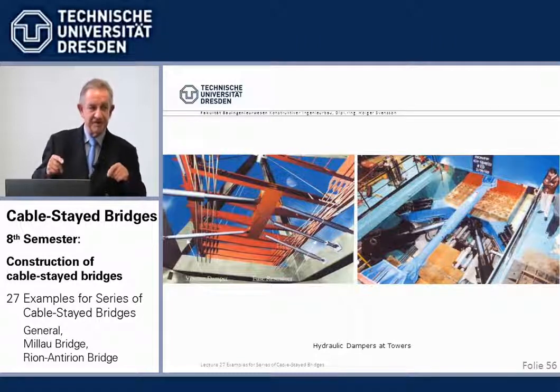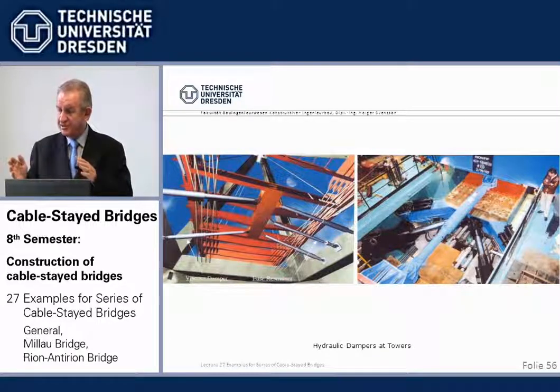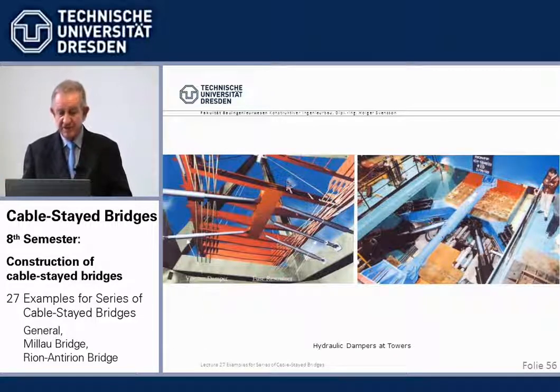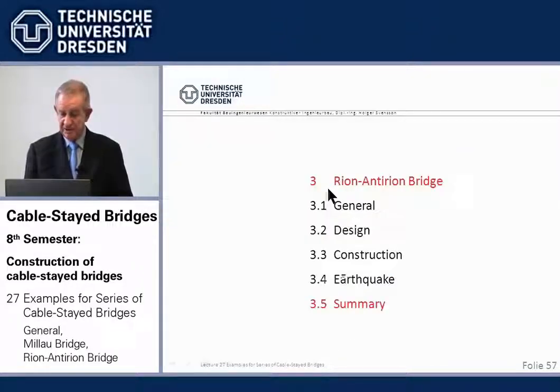However, in transverse direction we need something, not just bumpers that would take off the towers. In transverse direction we have dampers, hydraulic dampers and springs and so on to dampen the beam. We see it here and there. It's all in more detail in the script.